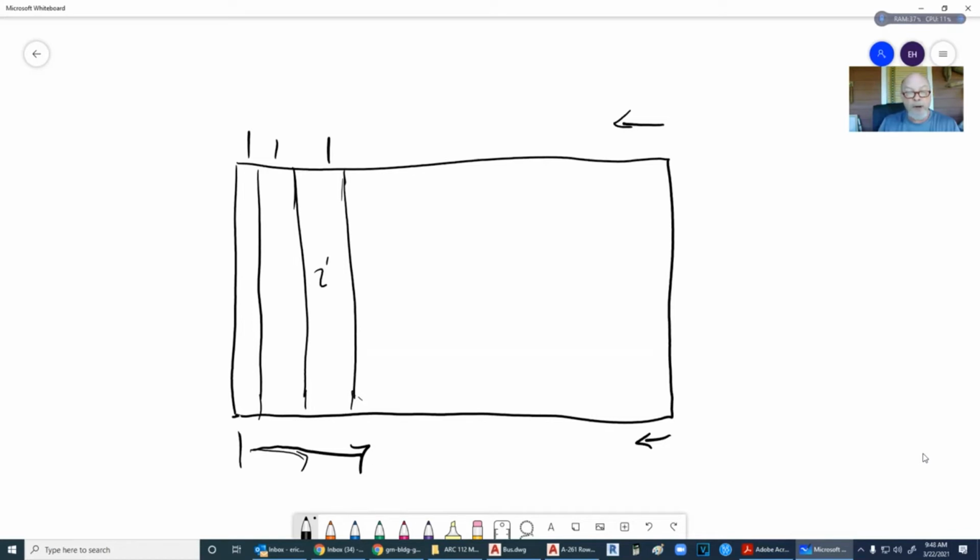You've got to make some rules when you're doing these types of things to ensure that you get these laid off in the right direction. We could have gone with a single top plate here, but because they shifted these, the studs didn't fall in line with the floor joists. Now we had to use a double top plate so that everything worked out correctly. Even if we got the trusses perfect like this, because these were off, the building inspector would not accept a single top plate.